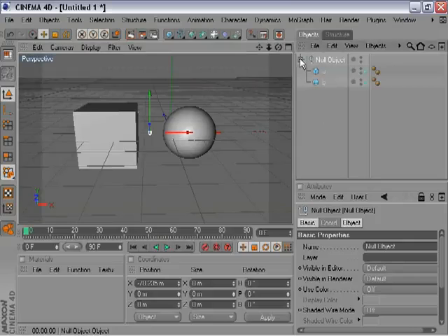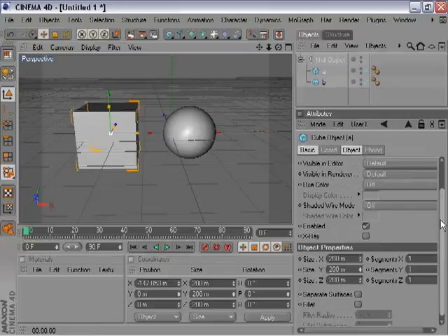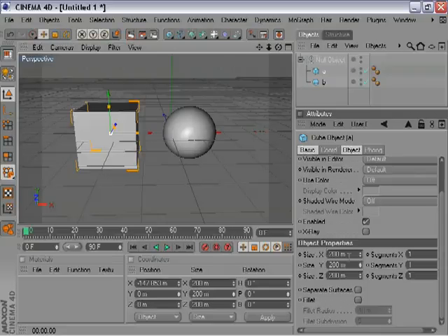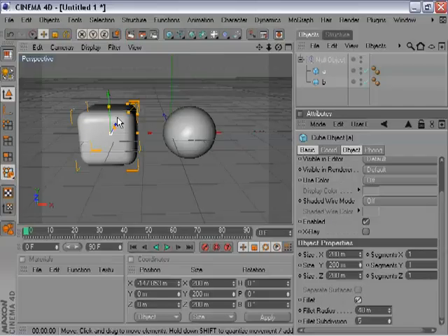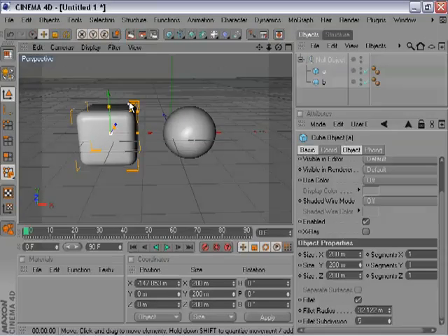The Attributes Manager though is, and this basically allows you to adjust the attributes of any object you select. For example, let's select that cube, and if I just scroll this up a little bit, you can see there's lots of settings in here that I can adjust, such as the size of the X, the size of the Y, size of the Z. Should things be filleted, if I click that, you can see extra things happen to this cube, where I can do things like fillet, and I can adjust all of this numerically or purely by eye if I wish. Coordinate system we've already had a look at. Materials is where you create materials to add to your objects. So that's all fairly simple stuff, and then you've got different ways of selecting things on the left hand side.